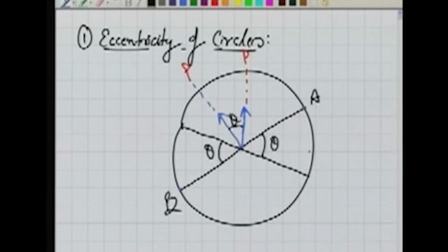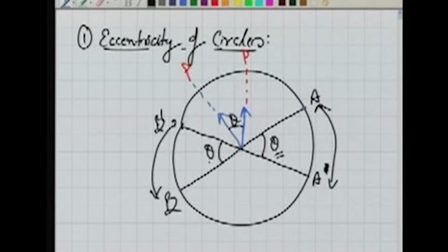So we take the readings at A dash and B dash. The vernier A reading is from here to here, and the vernier B reading is from here to here, and these two readings give us the angle value theta, which is the same as the angle between these two ranging rods at O, where the observer is.